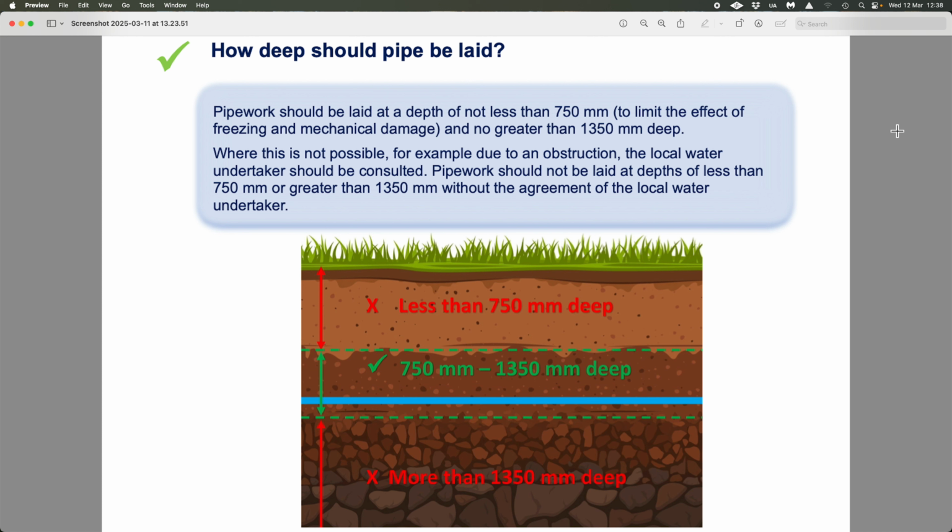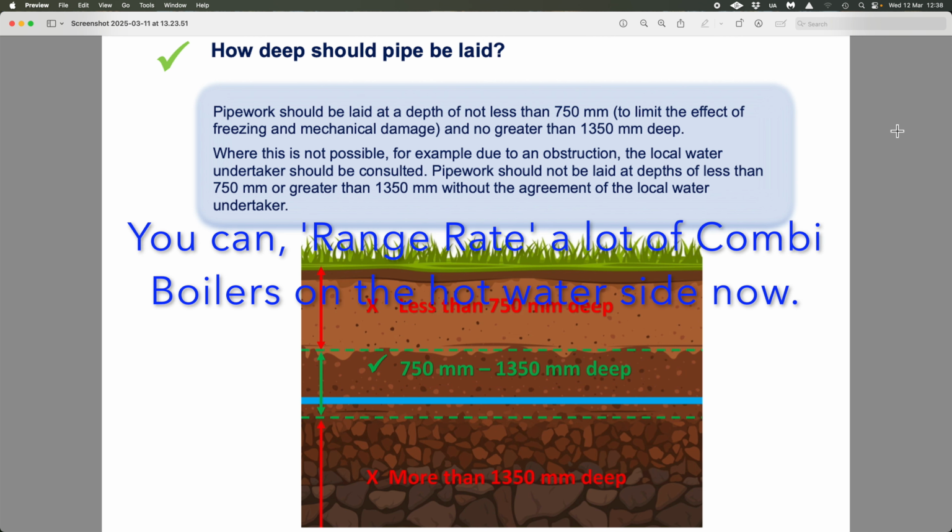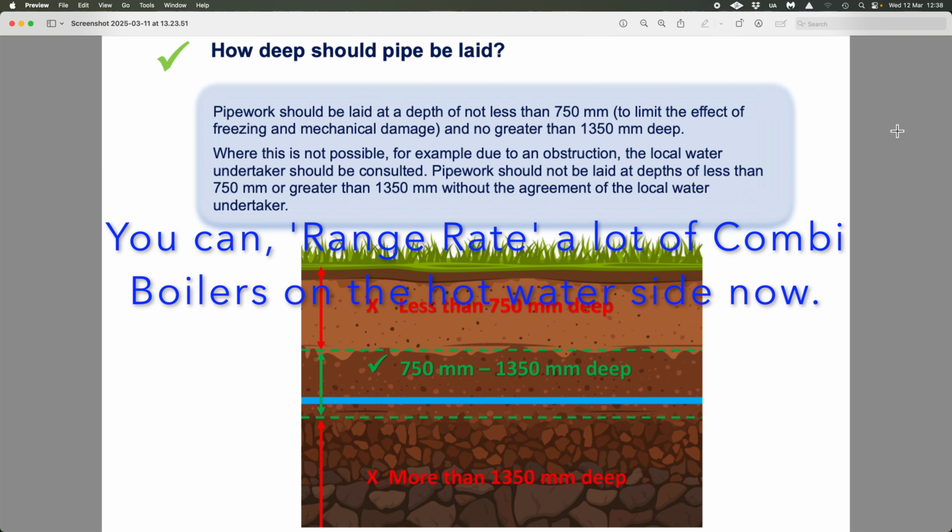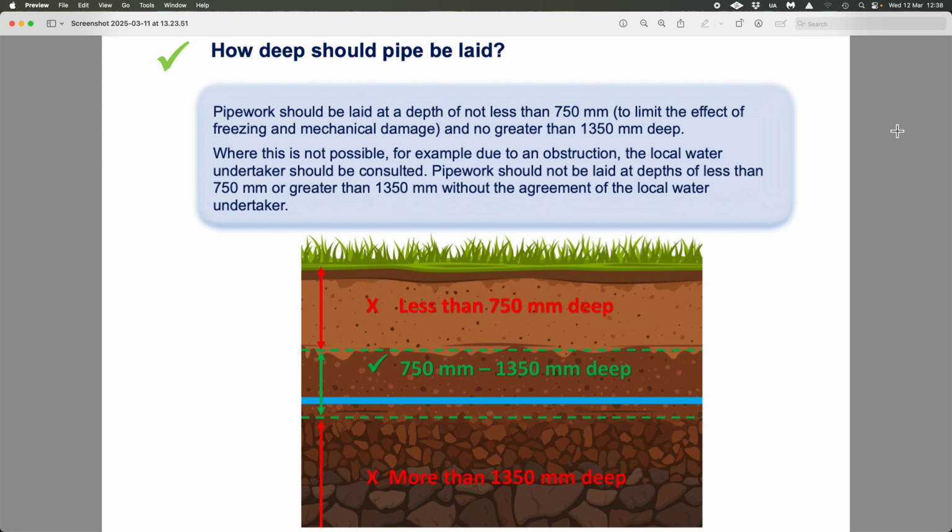I like that on combination boilers because it's under dew point, and dew point, as we know, is 54 degrees. So even in hot water mode, your boiler will be condensing, which is exactly what we want. So we're trying to squeeze the maximum amount of efficiency out of it. So we can do a few calculations, but I'd like to kind of explain a little story why I think people get this wrong so many times.